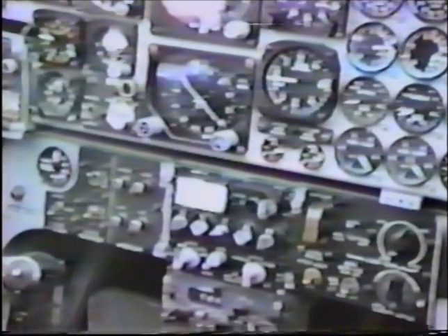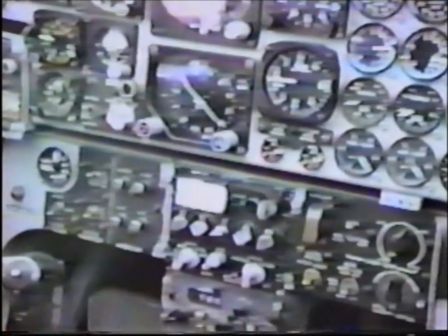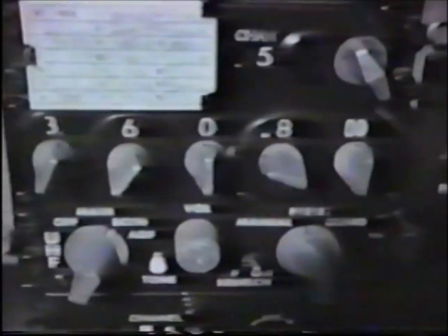The instrument cockpit check is required on every flight and is used to check your communication and navigation equipment. You can use the flight instruments check page in your in-flight guide to accomplish this check. On dual sorties, use challenge and response to complete the check. To check your communication equipment, simply call for taxi. If you can transmit and receive, your radios are good.